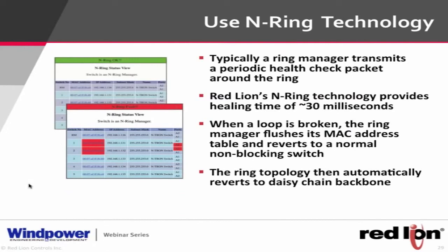And so you get reporting features with this that you don't get with RSTP, that you don't get with a lot of ring protocols. Like I said, if a failure were to occur, it would just occur, and you would have no way of knowing exactly where it is. You'd have to go hunt down the loss. So if somebody cut a fiber optic connection somewhere because they were laying a line down or something like that and cut your fiber down, you might not know where it is without logging in to each one of the switches and seeing which port's down.